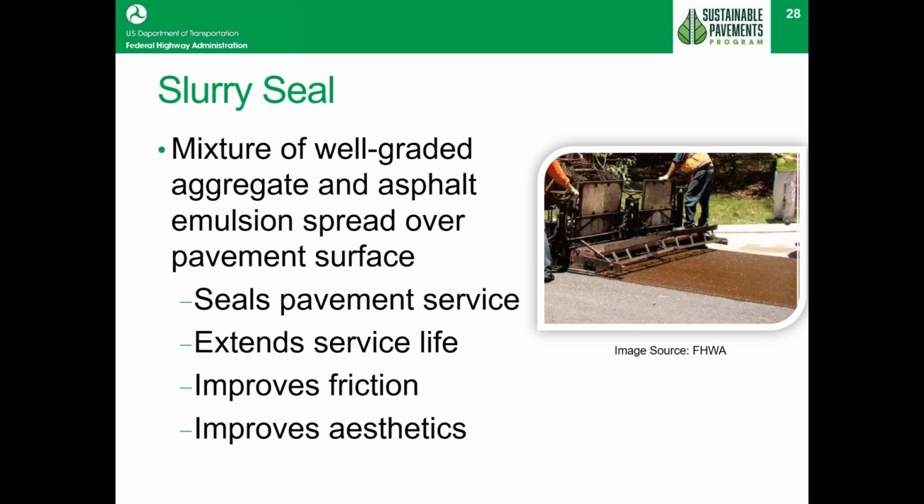It does provide a good seal. It can be placed in different thicknesses. You can add a little bit of thickness to the roadway and correct some of the profile issues in there. It's useful on the roadway if you don't have too many cracks in it.